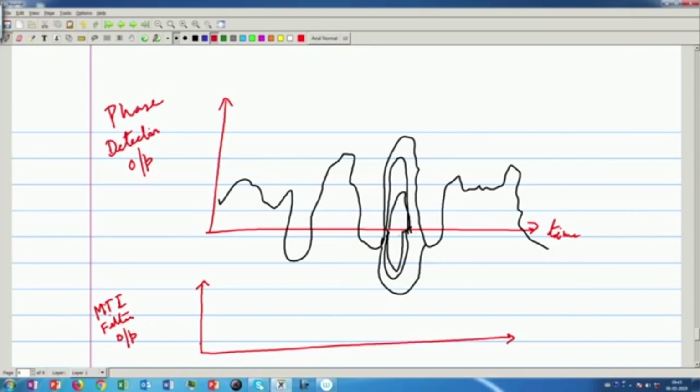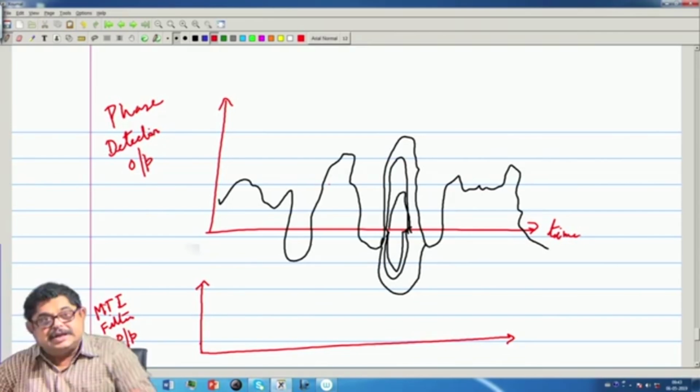from stationary target, and moving targets, you see the moving target phase is continuously changing, whereas the fixed targets, their phase does not change. So, for all pulses the phase of the stationary targets do not change, but moving target its phase is changing.